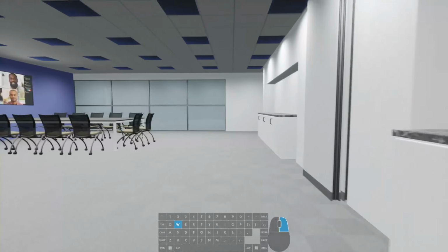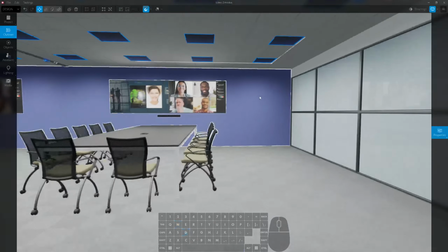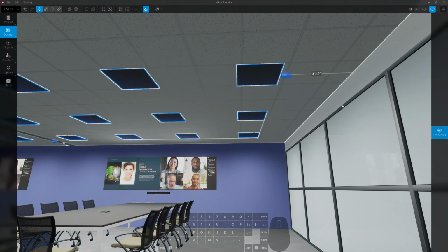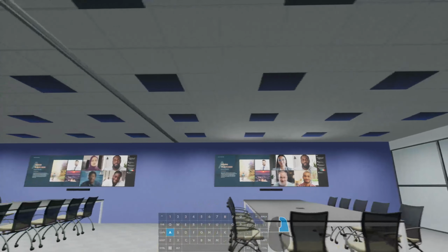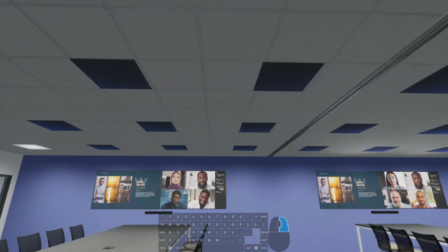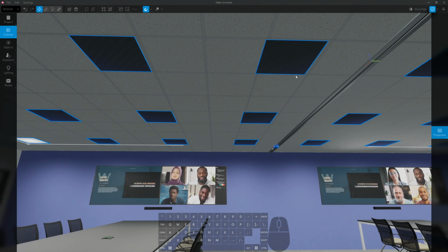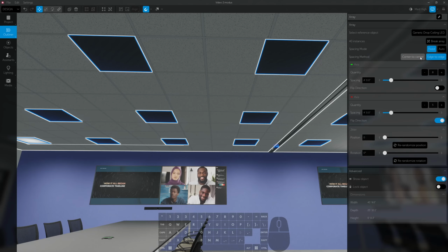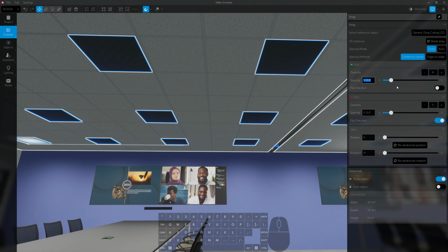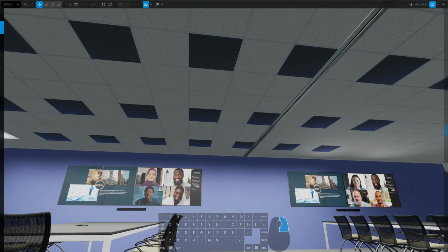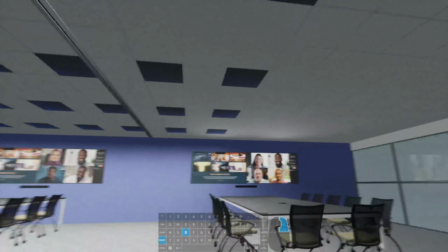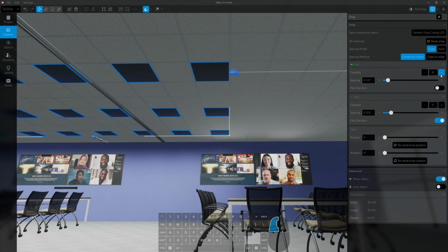down the way. We went from 4 to 8. And it's looking pretty good. Looks like we got a little bit off on our spacing here at one point. Let's do center to center spacing and do that 48 inches. Looks like it was taking into account the trim there. Now everything is going to be nice and evenly spaced.